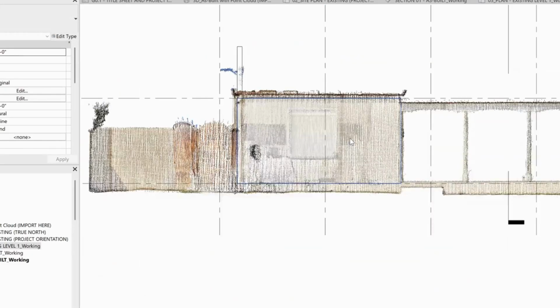If you guys can see it, sometimes the thing with point clouds is the more you zoom out, the better you see. When you start zooming in too much, everything starts to look the same. So I can tell that the window sill is here somewhere, and then it goes up to here. Here's my left side. Here's my right side. And then if I go back to place a window, I'll just pick something like this. And voila, there's my window.